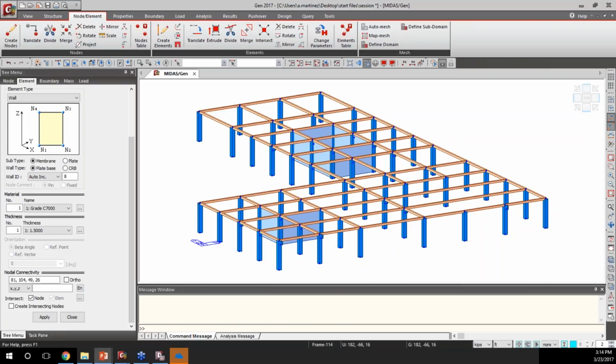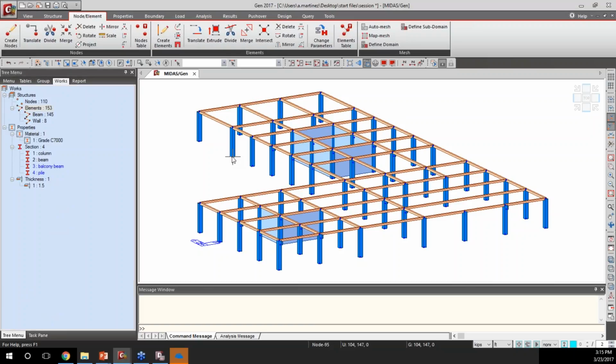So now we have the basis of the first floor, all the sections defined. What I'm going to do next is define the loads and apply the floor loads to this first floor. And then later I'm going to use a command called building generation that will allow me to generate copies of this story multiple times. And the reason I'm applying the load first is that this way it copies the load with it. All the stories that are generated from this blueprint will have the load applied as well. And so I don't have to go back and individually apply floor loads to every one.